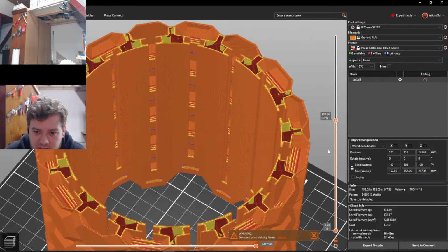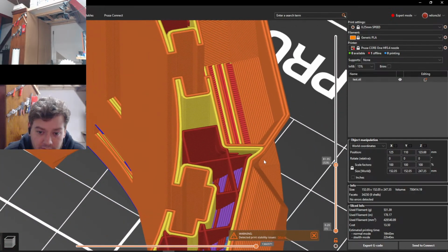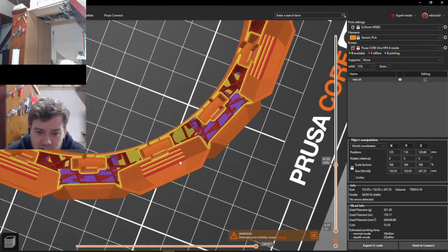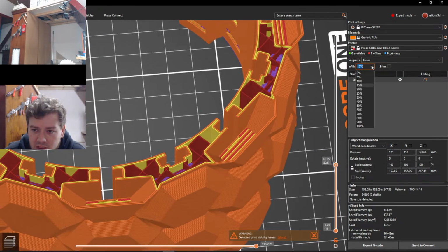And if I can get the inside better, you technically don't need infill. You need one small infill point here, and this is all the infill you need. Technically you can remove almost the whole infill, so you can say infill 0.